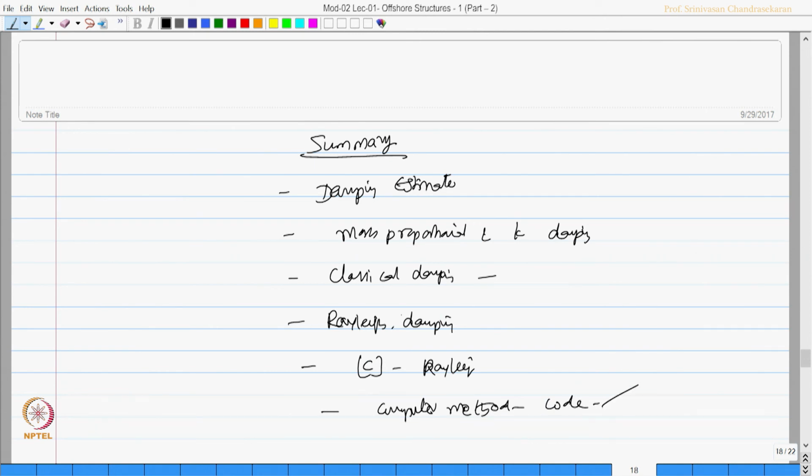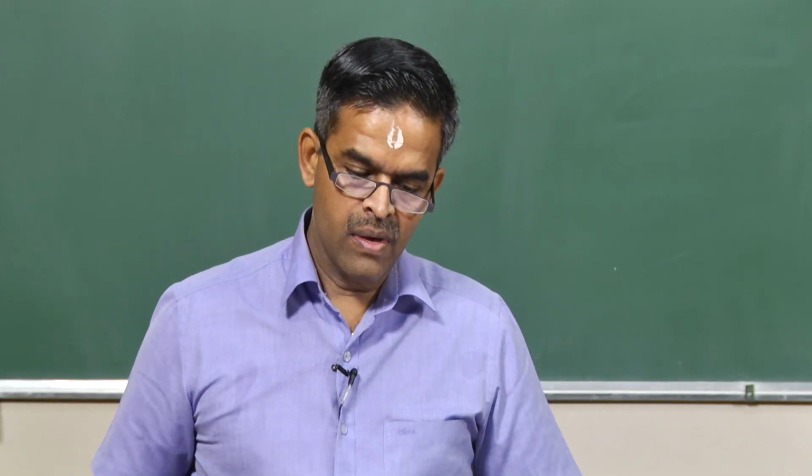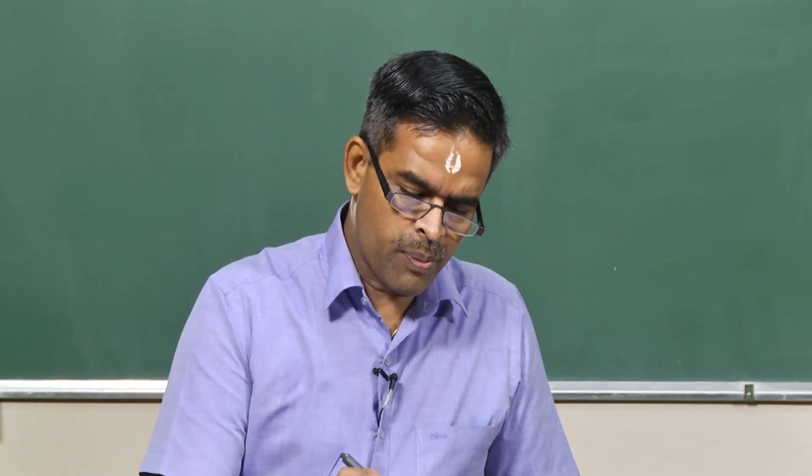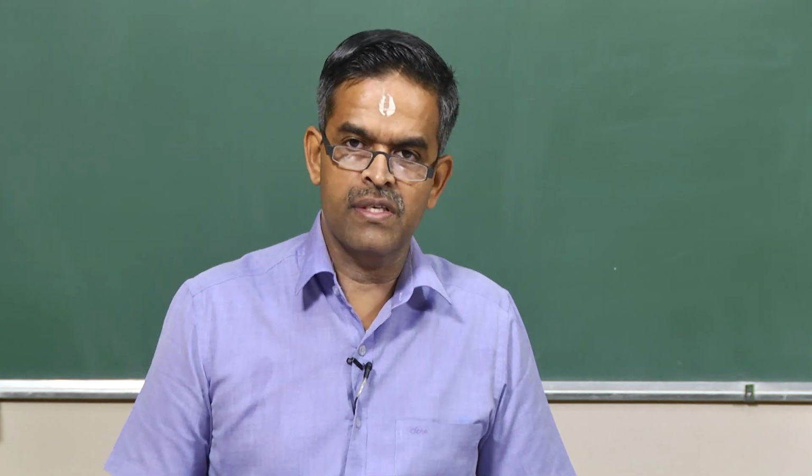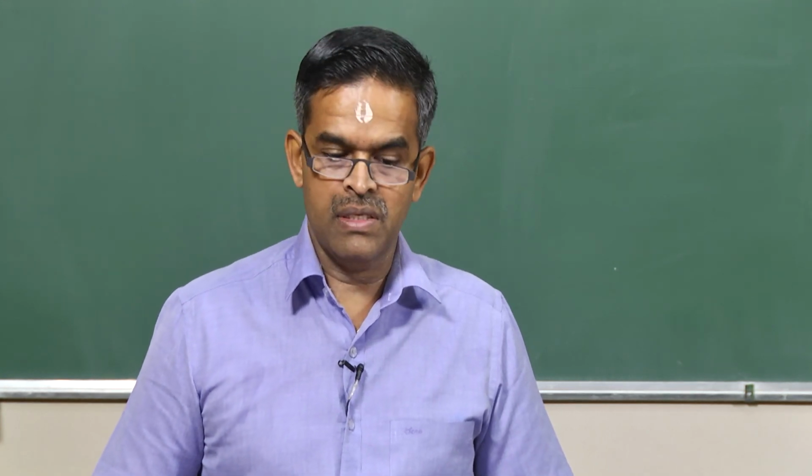We solved the problem both by hand and by computer code, and we found the answers agree closely with them. I hope you will be able to program this in MATLAB, do a couple of problems, and realize how easy and convenient Rayleigh damping is for damping estimates in offshore structures.